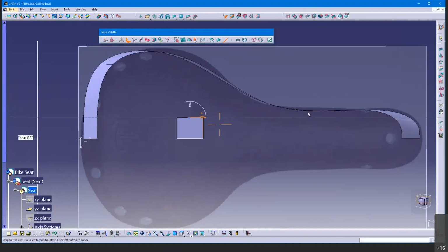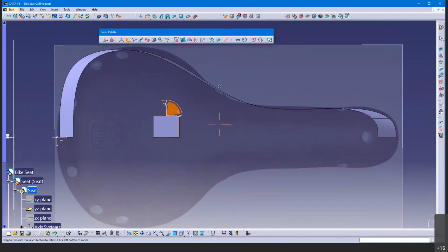I wouldn't do less or more, but you can end up with more and you just end up with bad surfaces. I see so many students try to make good surfaces by just fitting in more control vertices and more hull lines, and that's not the answer. The answer is always fewer. The fewer you can get away with, the better.